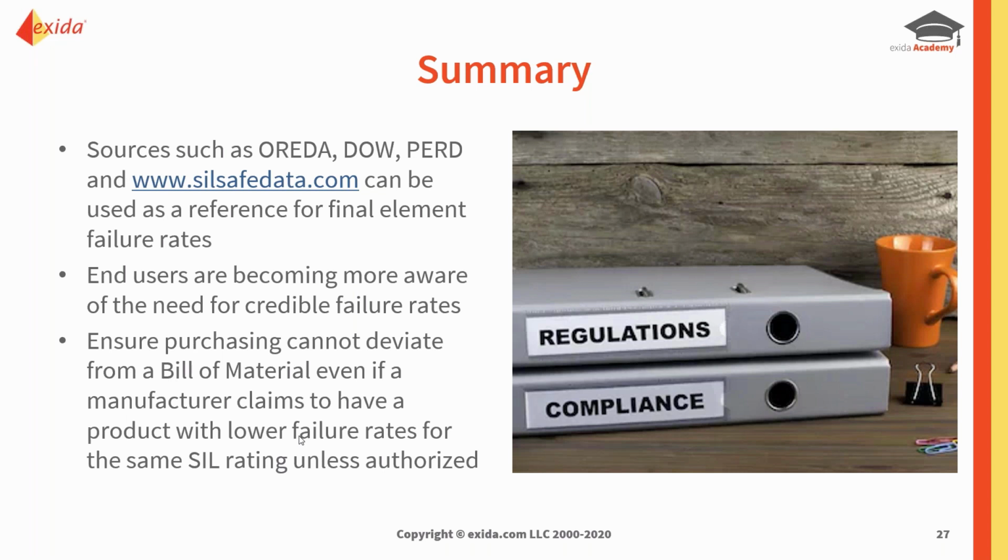Sources, IOGP, OREDA, PERD, and now you can use exSILentia to just compare. So if you've got a number that you think looks a little too good to be true, go and compare it and see if it lines up. If it doesn't, as I said, if it's an order of magnitude outside, then it doesn't pass the smell test.